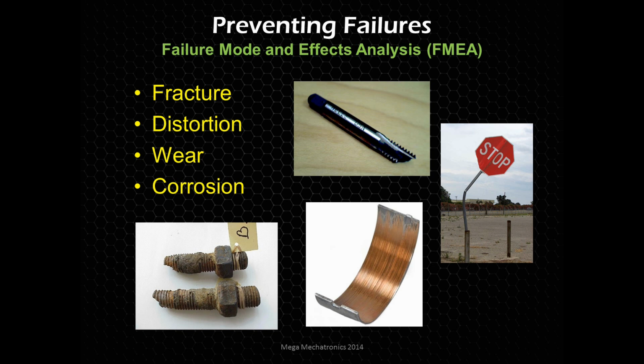And corrosion. What happened there? Was there galvanic corrosion? Were there dissimilar metals? Did the paint chip off? Did you not paint it? What type of environment? Was it designed for fresh water but was brought to salt water? And things like that. So you need to find that root cause. Why did it fail? Why did it wear? It broke, but it broke because of this and this. And going down the line, it started pitting. The material was defective.